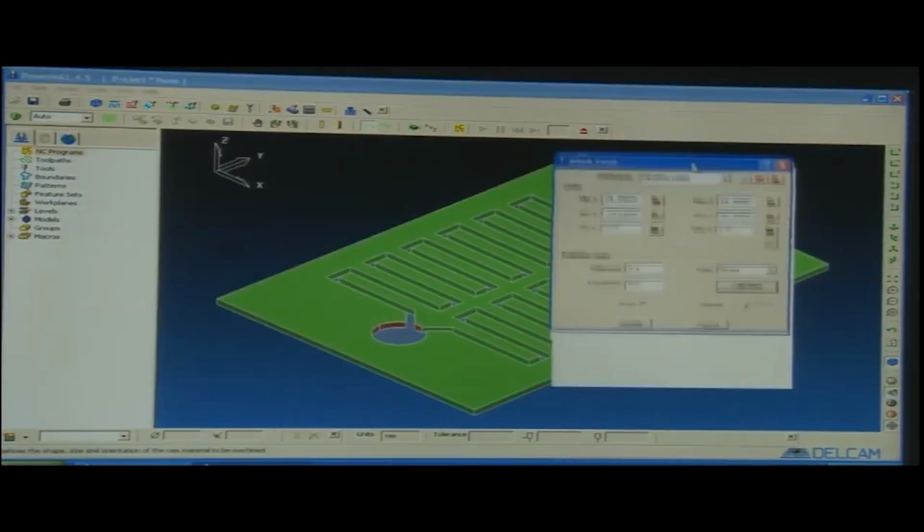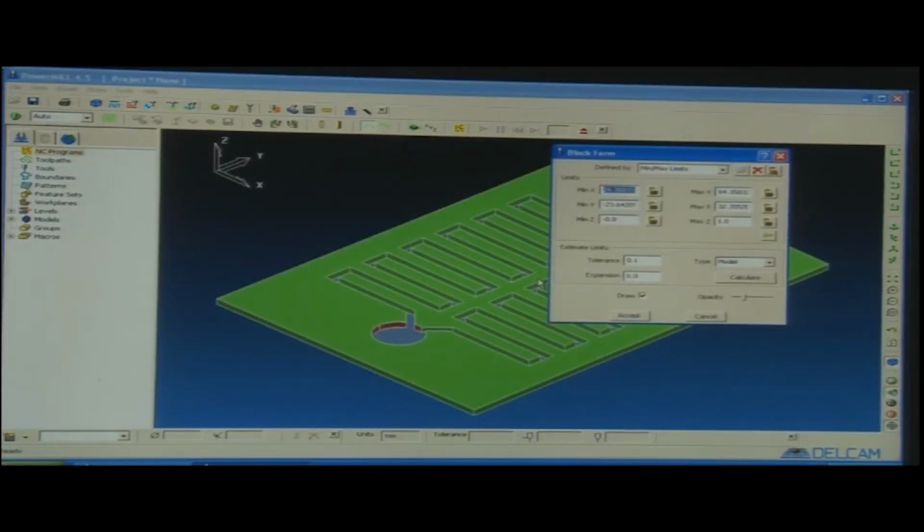So, similarly, we can pick the center for the present job as well, that we are going to manufacture on the CNC machine. When we talk about the center or referencing, normally it is important to consider the reference between the tool and the job. That is, at what point the tool touches the job has to be very well taken care of. I am again repeating that, because this is a very important point.